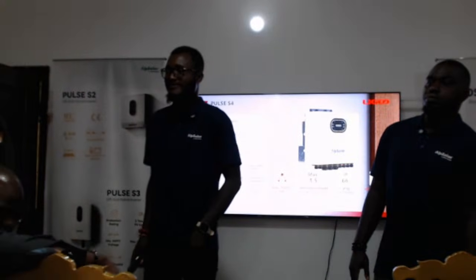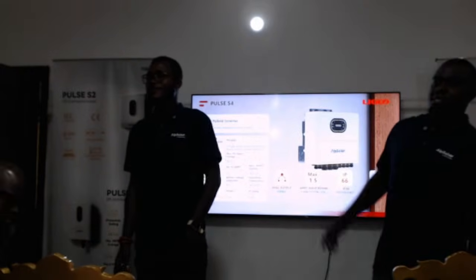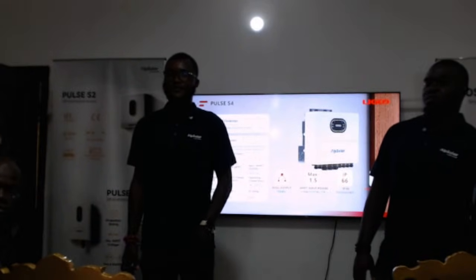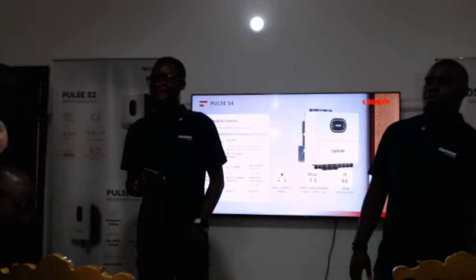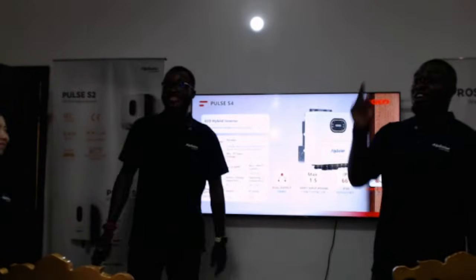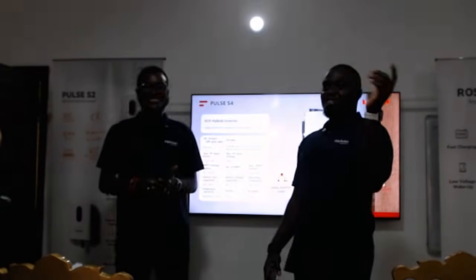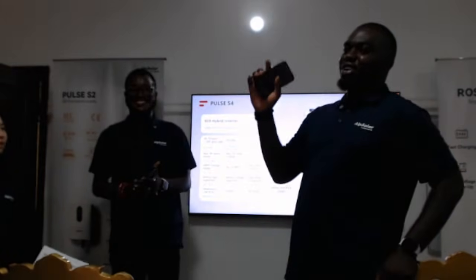Sorry, the wake up function, is it automatic or do you have to set it? No, it's automatic. It's default. That makes sense, that means you took our feedback. Yes, sure, wake up from PV and grid. The wake up function is important because it can give you problems on site too. If the PV is not sufficient, you have to wait for grid. You have to wake up the battery once the battery BMS is at low voltage.